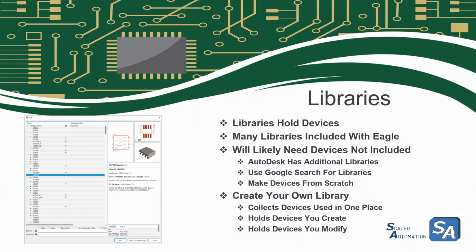And then the other thing, it's really cool, and we'll also look at this today, is that it can hold devices you modify. The library that something came from might not have something you want, or might be too complicated. There's a number of reasons why you might want to modify a device. So you put those in your own library, give it a unique name if you like, and then you can use that device that you modified. And we'll show some examples of that today too.